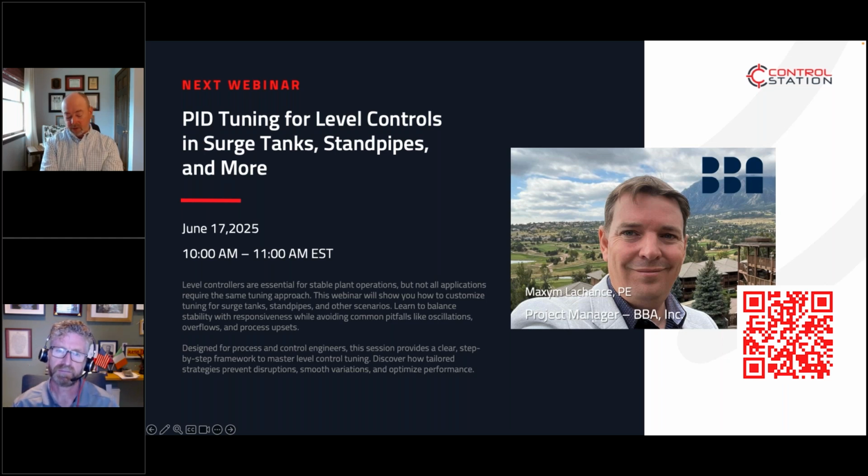Rather than put too much focus on the valve vendors themselves, I think more focus in the engineering design phase is where you can mitigate stiction. Make it a design criterion that you choose actuators and positioners appropriately.